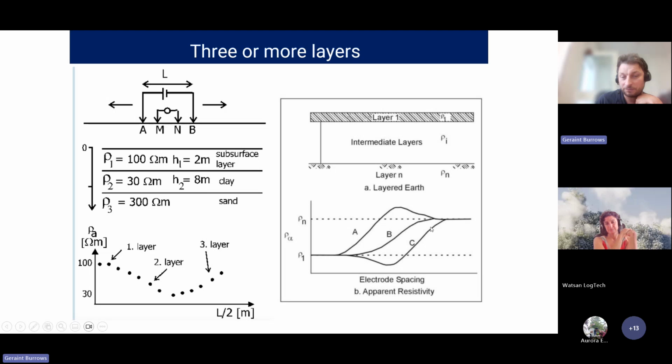And this curve might keep going up and up because the resistivity of the hard rock could be in the tens of thousands. So it's these kind of curves that we'd be looking for to help us to determine the depth to weathering within a crystalline basement weathered setting, where we can suggest a three-layered model of unsaturated, slightly more resistive, saturated, weathered, and then crystalline rock.